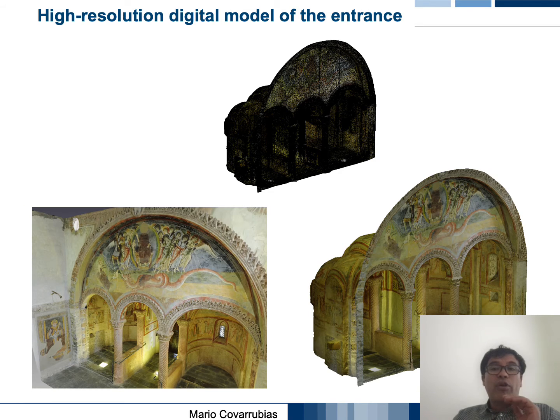Indeed, a photogrammetric project with such images usually requires a reduced number of shots compared to traditional photogrammetry with frame, also called central perspective images. However, fisheye images require a different camera model during photogrammetric processing, which is currently supported by a limited number of commercial software packages.